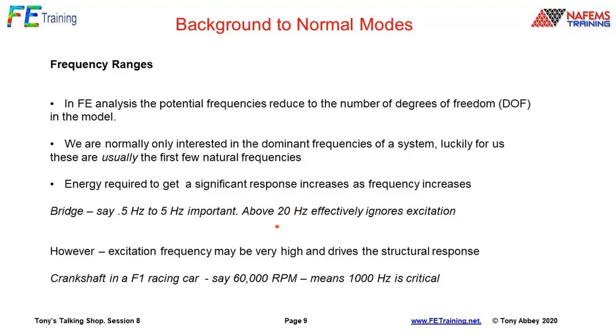But we've got to be a little bit careful. Sometimes if we've got a driving input, then sometimes that high frequency content is important to us. So like a racing car, 60,000 RPM, 1,000 hertz, that would then become critical to us. So generally we're thinking these responses tailing off, but we've got to watch out for specific excitation frequencies.